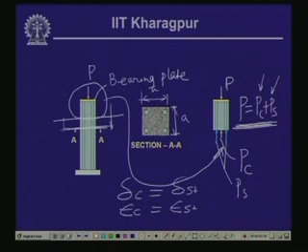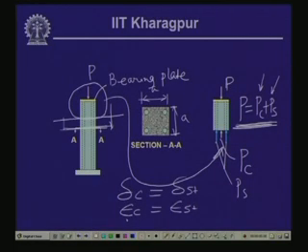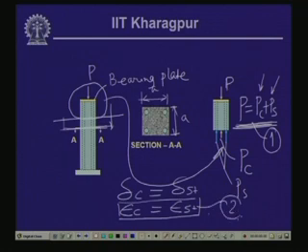And this strain, as we had done last time, we write in terms of stresses using Hooke's law, which we call the constitutive relationship between stress and strain, and that will give us another condition for forces between the concrete and the steel. Now that we have one equation from here, we get another equation from here, and using these two equations, we can solve for PC and PS.